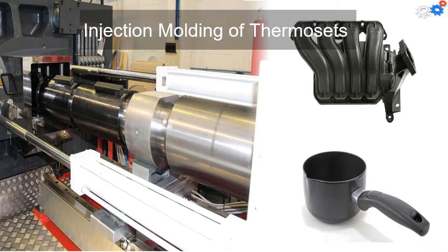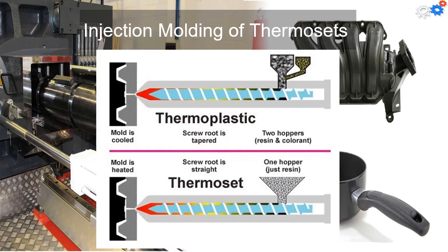For injection molding of thermosets, equipment and operating procedure must be modified to avoid the premature cross-linking of the thermoset polymers. Usually, the system has a shorter barrel length. Temperatures in the barrel are relatively low. The melt is injected into a heated mold where cross-linking occurs to cure the plastic.